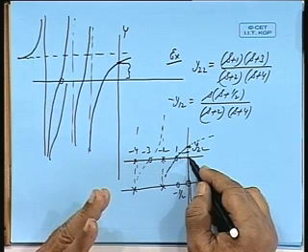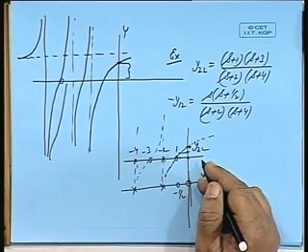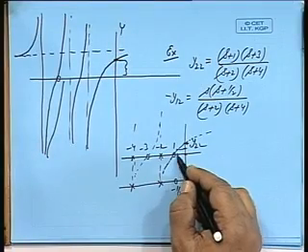Mind you, there is no pole I am weakening, it is removal of a constant. I can remove part of a constant or weaken any pole, all right. That pole, depending on the network function, can be at a finite point or at infinity or at 0, depending on whether it is an admittance function or an impedance function. For an RC impedance function, the pole can be at the origin, but there cannot be any pole at infinity. Similarly, for an admittance function, pole can be at infinity, but not at 0. First one has to be a 0.